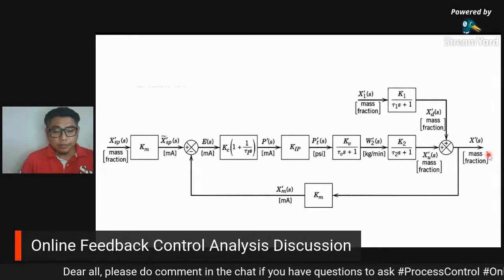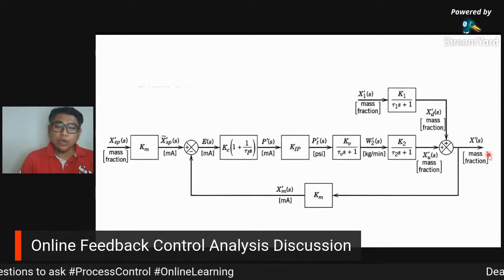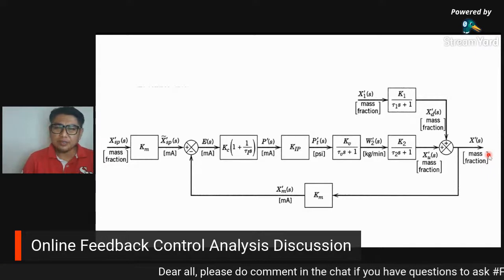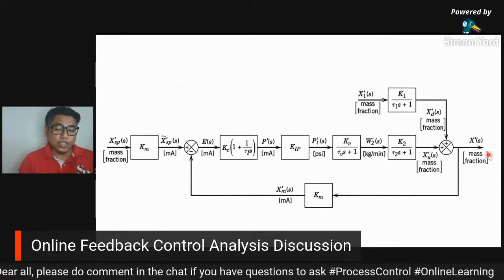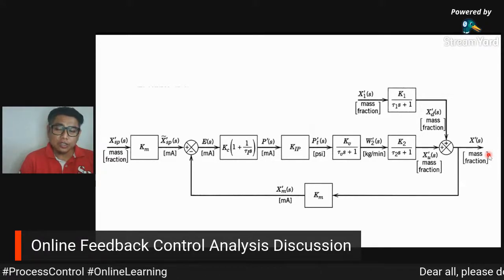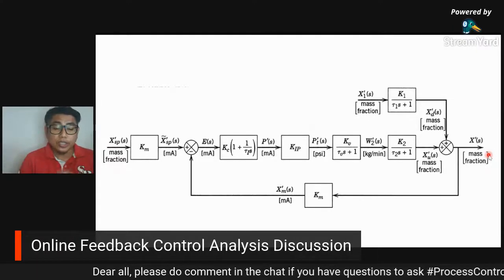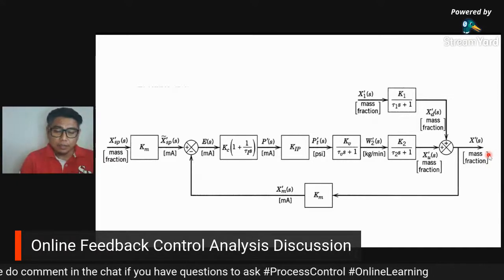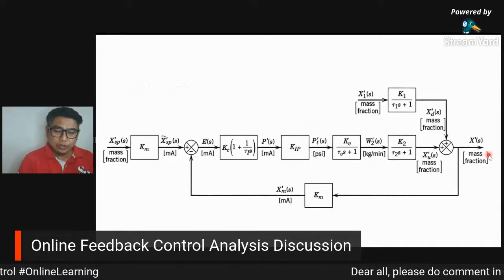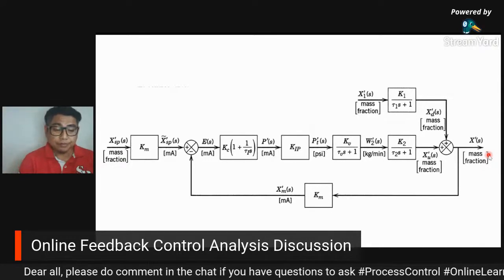That's all direct. Whereas for the Ziegler-Nichols, for the online, you need to do a lot of things. First, you need to do the online tuning first. It's not tuning, it's basically online tuning, finding the online tuning parameter, where you need to change some of the tuning parameters to make sure that you obtain a constant oscillation response of your output or of your control variables. And from that, you will do certain analysis, finding the ultimate period and also finding the ultimate Kc, such that it will give you that constant oscillation. And from that, you just substitute into an equation model. That's all.